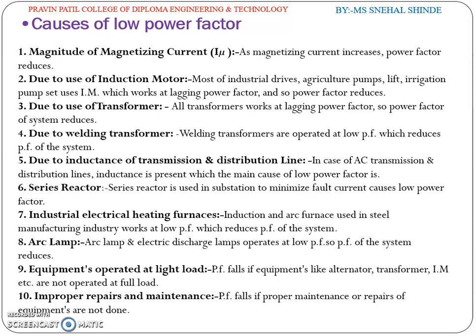Then the last point is improper repairs and maintenance. So power factor falls if proper maintenance or repair of the equipment is not done. All AC motors, except overexcited synchronous motors and certain types of commutator motors, and transformers operate at lagging power factor. So the power factor falls with the decrease in the load.